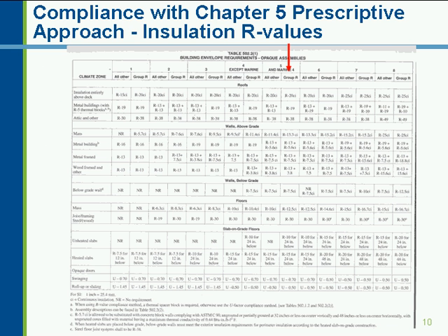If we look at the table, table 502.2(1), this represents the insulation values based on the type of assembly in the building. For example, it's split up into roof assembly, walls above grade, walls below grade, floors, and slab-on-grade floors, and then down at the very bottom are doors, which are typically opaque doors, whether it be a man door, a solid man door, or roll-up door, but those are opaque door requirements. Each of the categories has different types of assembly.